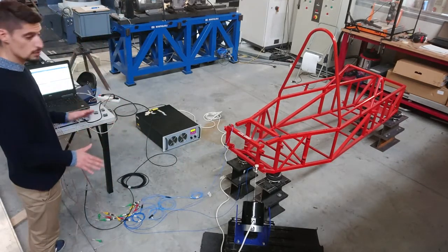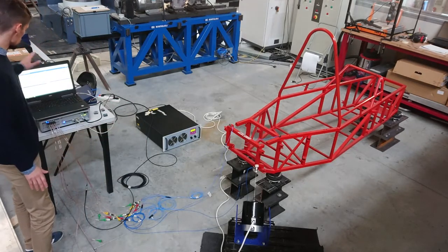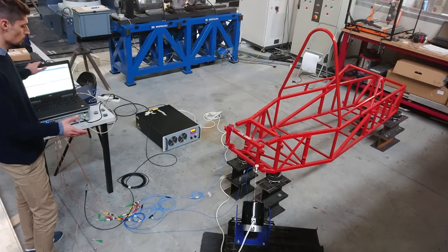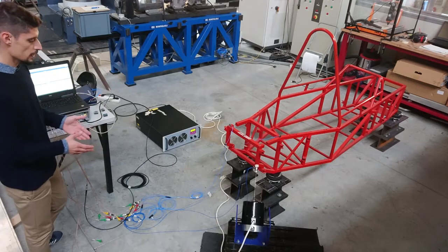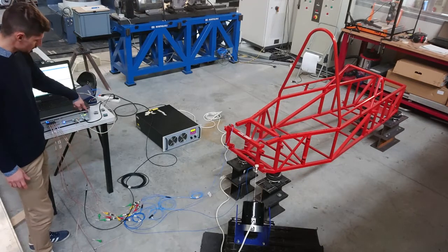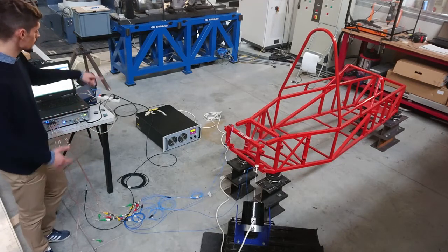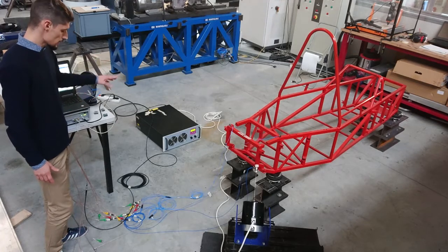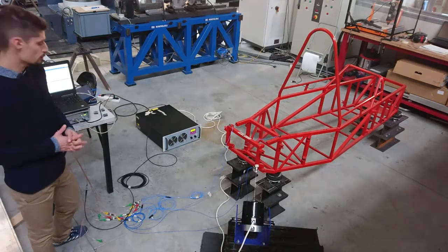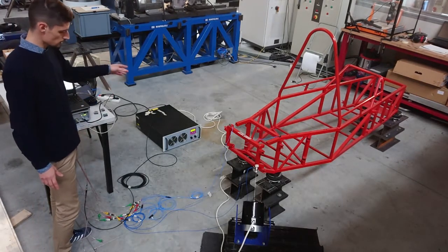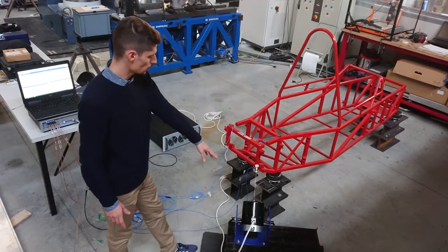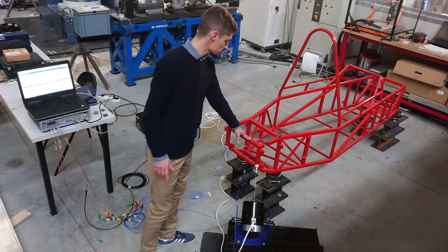So in our case, the measurement chain starts from the computer. We decide the way by which we want to drive the shaker, so with a random profile, sine profile, burst random profile, and so on. The computer talks with the SCADAS, which converts and sends the signal to our amplifier. The amplifier, depending on the gain that we have imposed, corrects and sends the input voltage to the shaker. Therefore, the shaker excites the structure, which starts to vibrate.